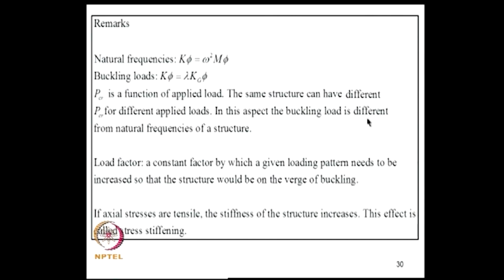In this aspect, the buckling load is different from the natural frequency of a structure, whereas the natural frequency of the structure, unless you include geometric stiffness effects into that, is not dependent on applied loads. So, load factor is a constant factor by which a given loading pattern needs to be increased, so that the structure would be on the verge of buckling.